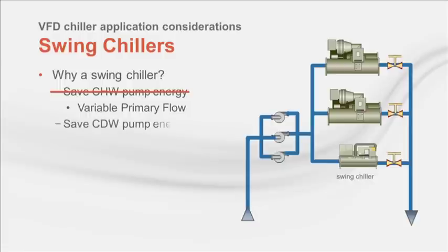The second driver is similar to the first, condenser water pumping energy. Once again, large steps of constant condenser water flow result in excess water flow and pump energy use at part load conditions. The use of either more optimized Earthwise design flows of 1.8 to 2.5 GPM per ton or fully variable condenser water flow for high design flow systems greatly reduces condenser water pumping power, eliminating the second driver.